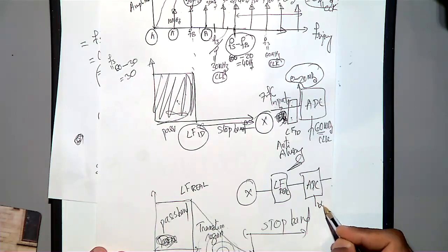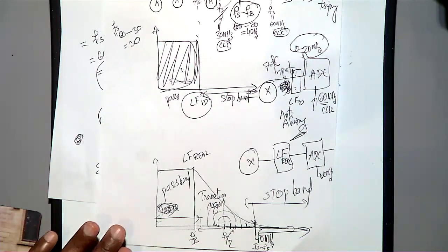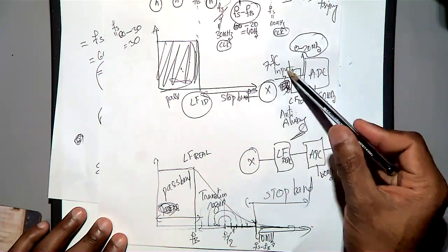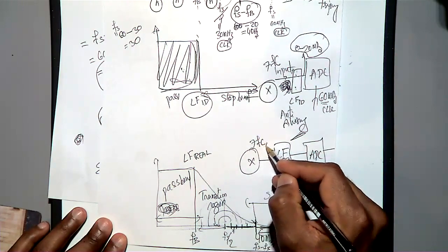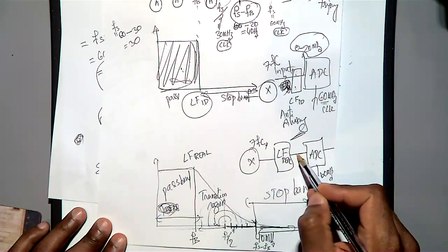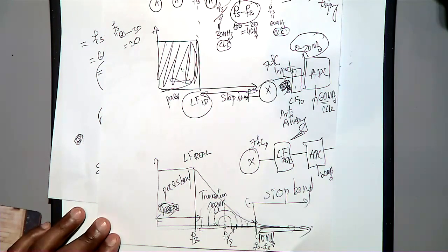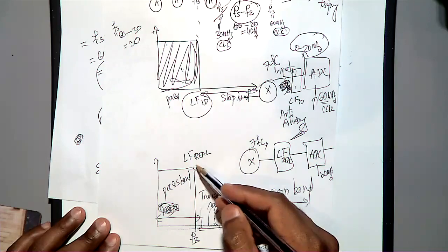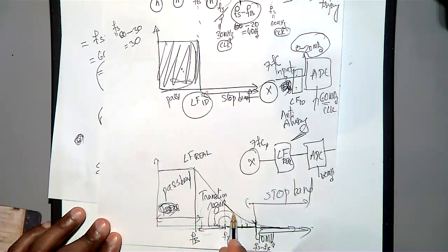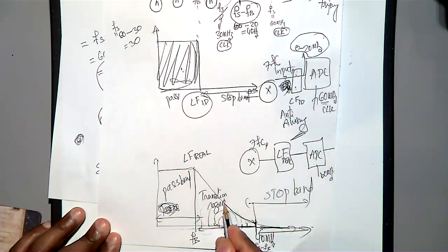Then here it is 60 megahertz. So now my question is, here your X got so many frequencies, like 7 frequency components. So then my question is, here what will happen? So what you will see? Will you get this region in the signal? Yes, because these frequencies will be sampled and folding back to this region. So you are actually getting some error, but then this region's amplitude is like this.